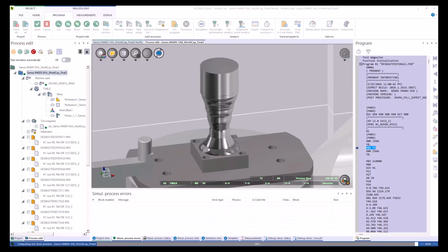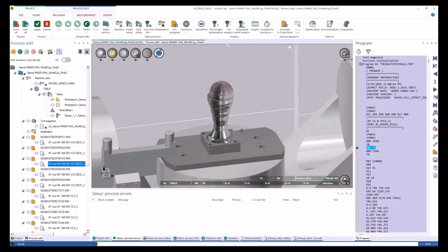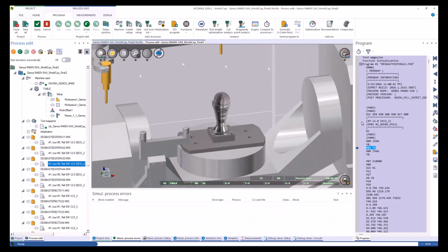Normally, it should run even quicker when you're also not utilizing Teams for screen sharing like we are. But as you can see, we already have stored material and jumping-in points for the end of each sequence. That's indicated by the rest stock icon, that gray L, next to each toolpath in the tree.